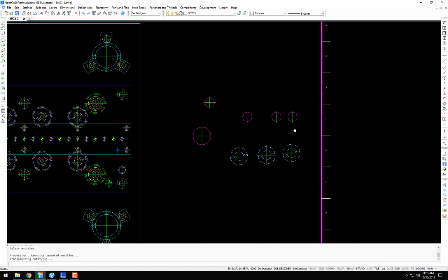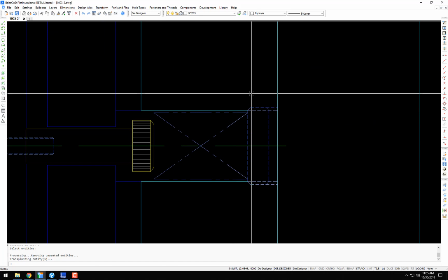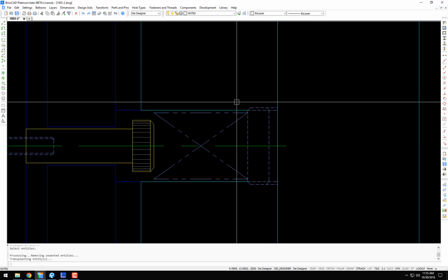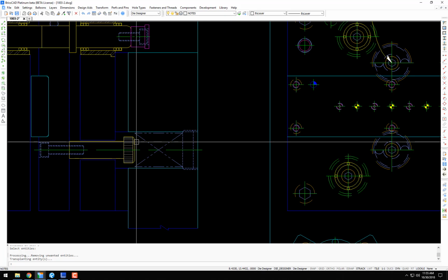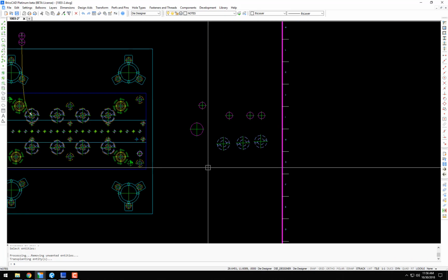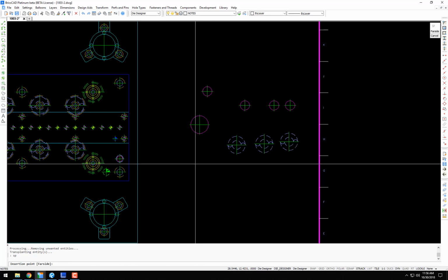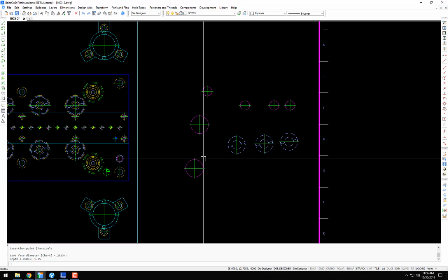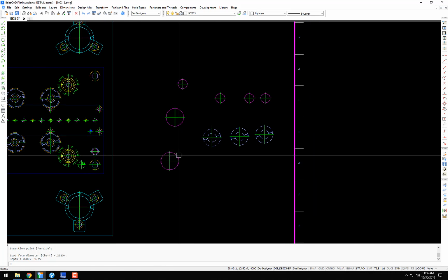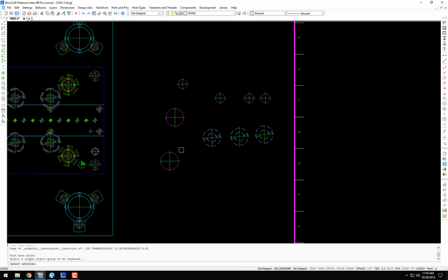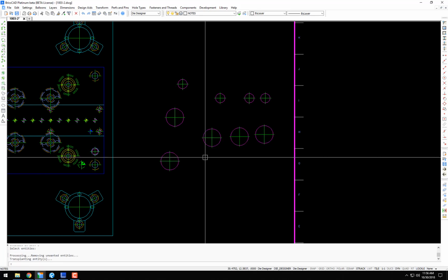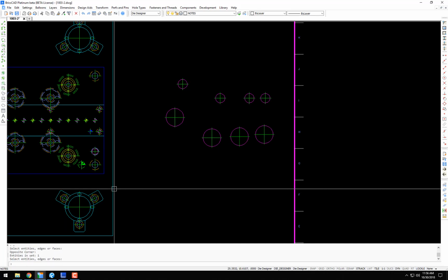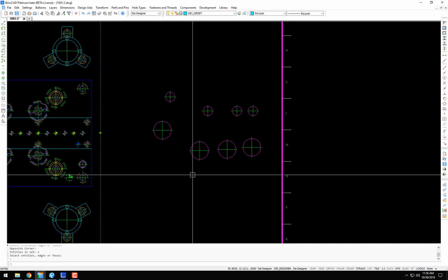Let's say we did not have a unified screw plug behind here. This was just a blind hole, what I would call a spot-faced hole into the die shoe. So I could just go spot face. We'll stay with the 1-inch diameter, and let's make the depth of that spot face hole, say 1.250, just a random number. Now I could use a search and replace and replace all those instances when I was detailing the die shoe.